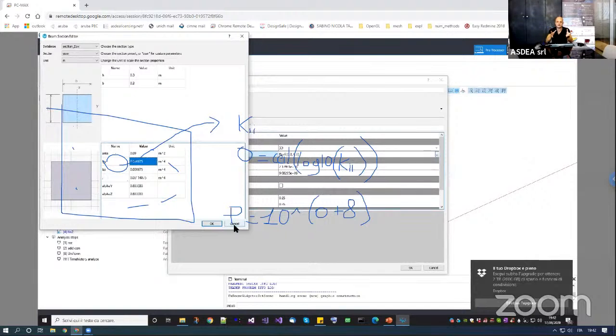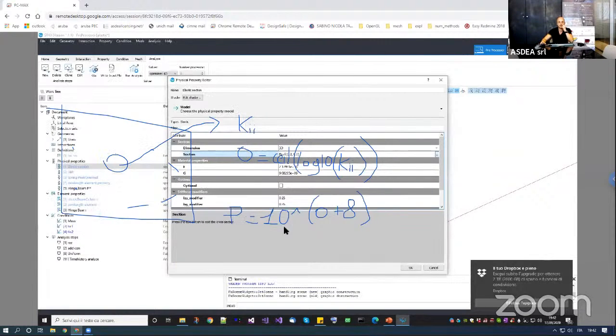It should not be exactly that value. It can be one order of magnitude more or one less, but not much different than that, okay? Since you do geotechnical analysis, you use mesh models, so don't take exactly the Young modulus. For example, if you are modeling a soil, you take the Young modulus and multiply it by the volume of the element. That can be a sufficiently realistic number for this value here. So let me just clean the annotation.